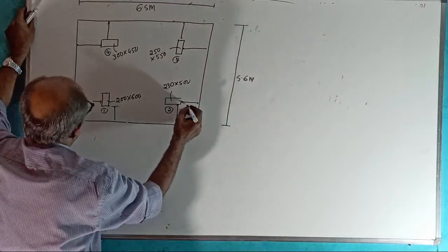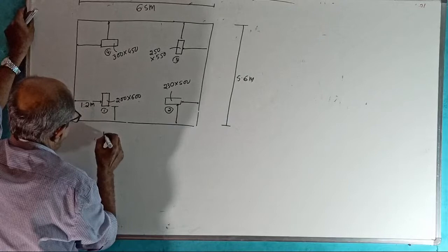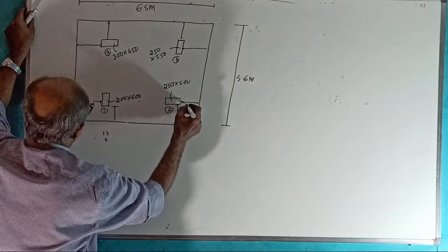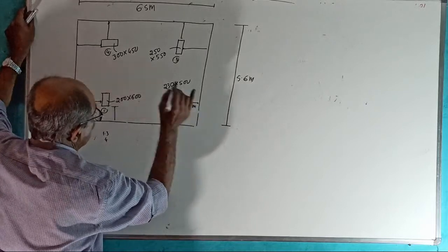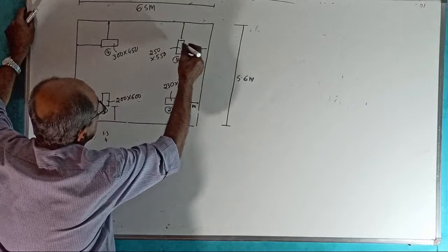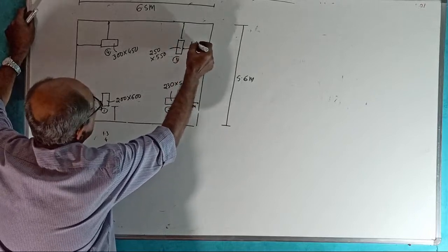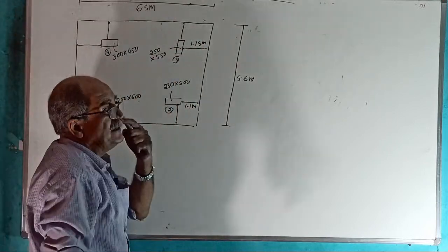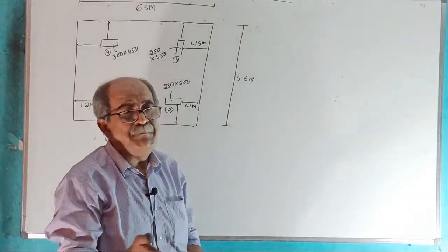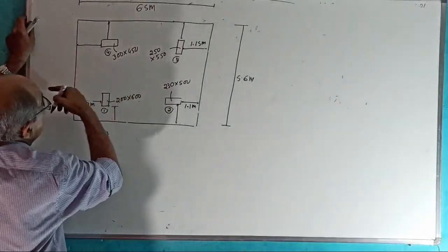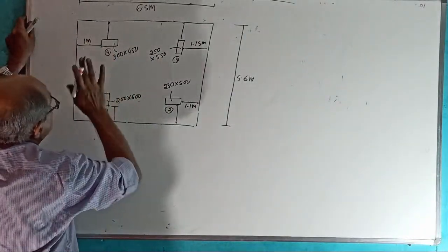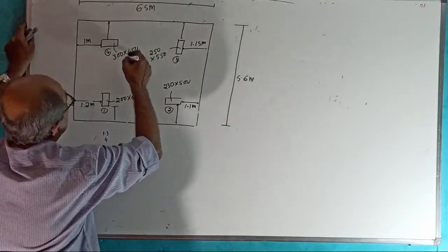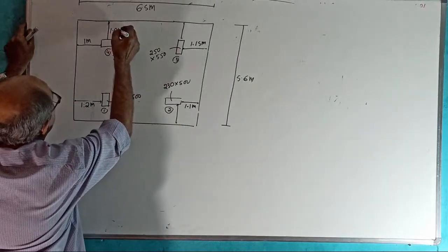If that is 1.2 meter, this is 1.2 plus 0.2, that is 1.3. This is 1.1 meter, out of scale. This distance is a little more, 1.15 meter. Little shifted. Suppose the 4 columns are correctly symmetrically placed, you are happy. And this distance is a little lesser, just 1 meter. These are the 4 column lengthwise distances. Widthwise, this is 1.05 meter.